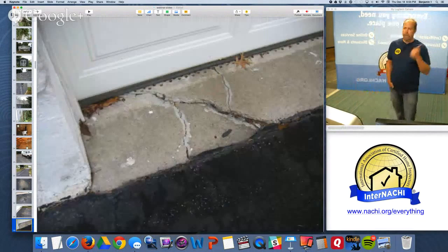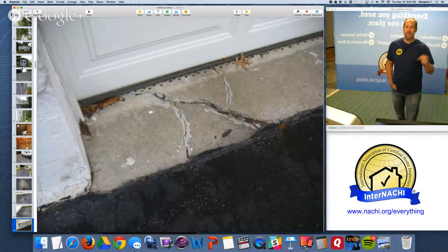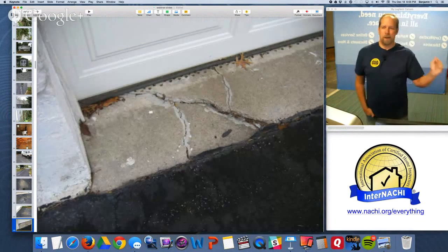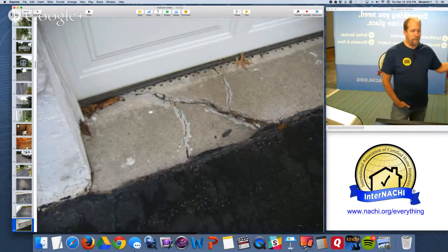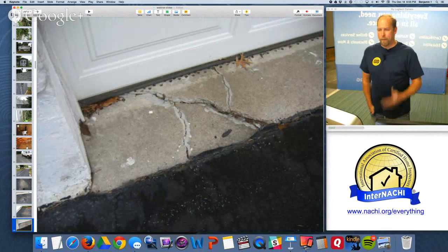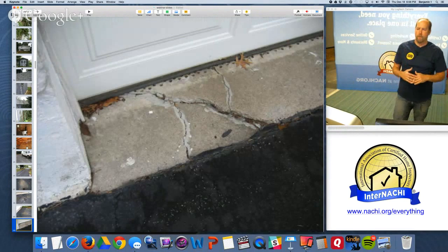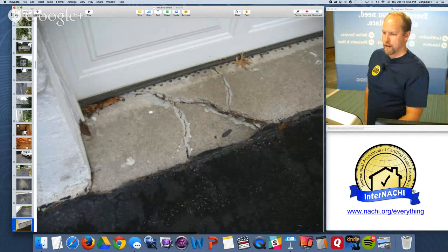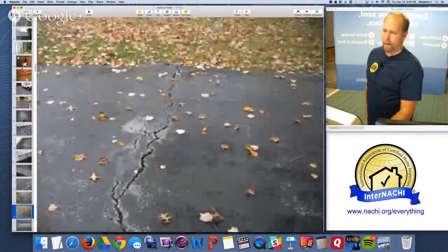Water has popped that front threshold area of the garage door, and they've drilled holes, drain holes, all along the front to catch the water. I don't know why they just didn't do a trench, a French drainage trench, with a metal grate, something. There are many different options to fix this problem where the driveway may be higher in elevation than the garage floor, or it could be sloped in where there's a negative slope towards the garage. Driveway's in poor shape. Some of the roots are popping up.